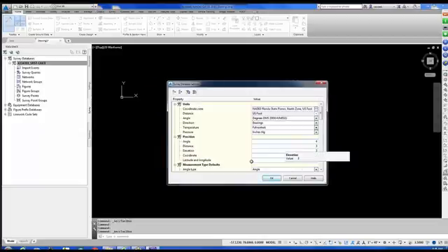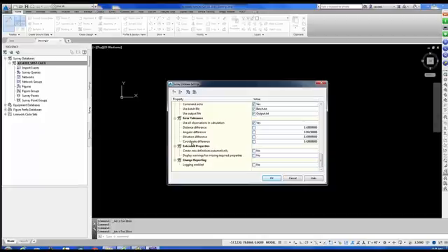Now, another very important step is you have to take the slide bar and slide all the way down the list. Under Extended Properties, you want to tell it to create new definitions automatically, and you want to display any warnings. What this does is there is data coming in that we call extended properties, things like what zone, whether it's a feature or whether it's a ground attribute. If we don't check this box, that information is not available to us when we pick on a point.